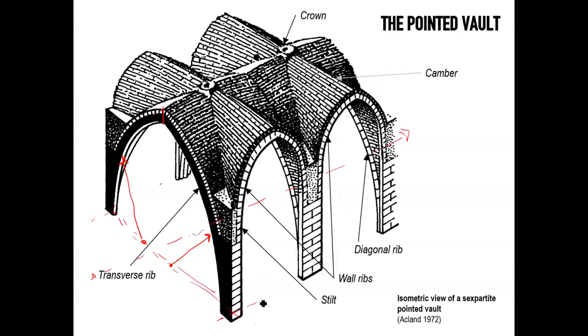But on the other side, we're not restrained anymore to have a semicircular shape. We can simply raise up the springing point, whereas here on a transverse rib we can start, for example, at this point. On the side aisle we can set up the arches facing the aisles to start at a higher level, and we can also not necessarily have the same curvature as the larger one.